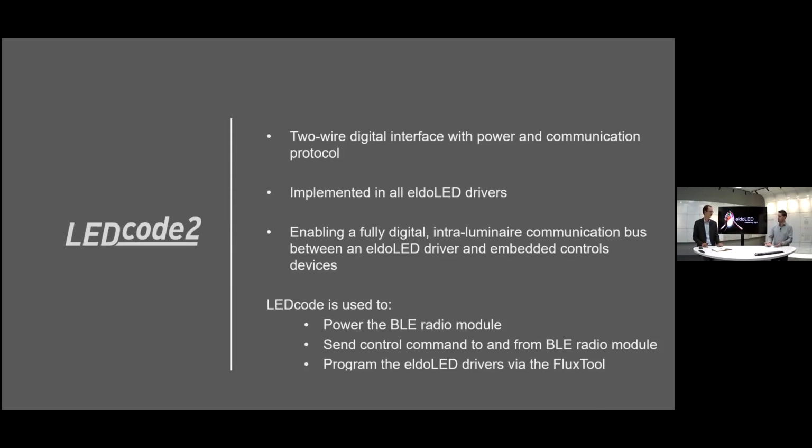Yeah. The OEM can make a luminaire, they can integrate the LED driver, they can sell it as a DALI driver, they can sell it with a 0 to 10 volt driver, and they can sell it with a Casambi enabled solution on the same certification. And that makes it very easy because it's just plugging in a 2-wire interface without changing any high voltage wiring. No line voltage, no mains involved, no certification impact. You can simply ship that same unit in the market as a Casambi controlled luminaire. And that is a huge advantage from an OEM perspective.